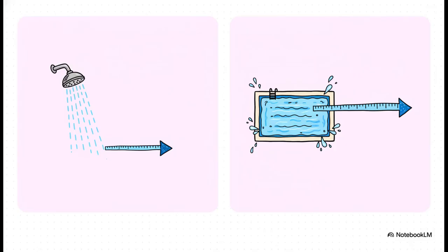Let's compare the indoor and outdoor safety bubbles for a second. Indoors, the safety bubble is relatively tight. Zone 2 for a shower only extends 0.6 meters past Zone 1. But for an in-ground swimming pool, Zone 1 extends a massive 2.0 meters out from the internal rim of the pool. The standard completely recognizes that the splash zone, the wet bare feet, and all those outdoor environmental factors create a seriously escalated hazard that requires a much larger protective footprint.